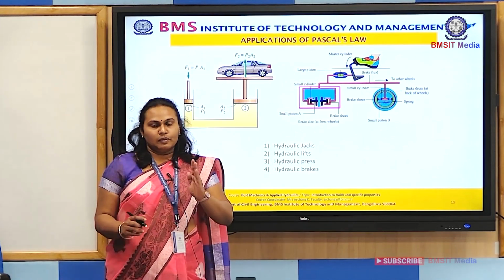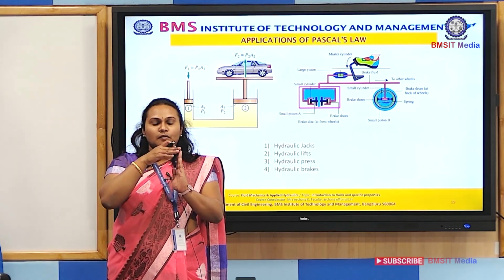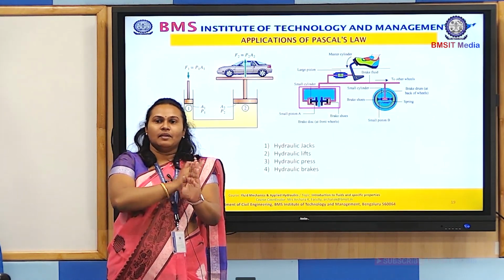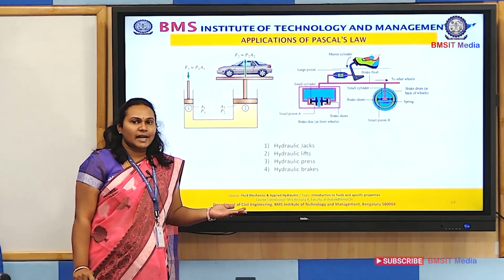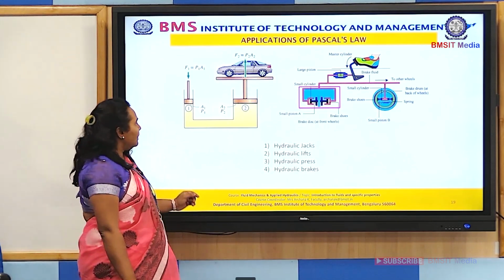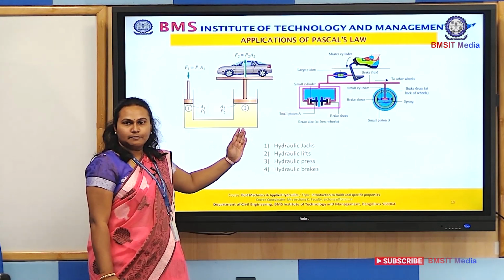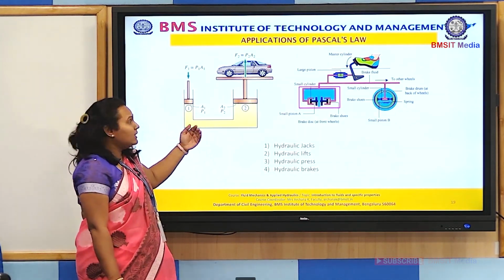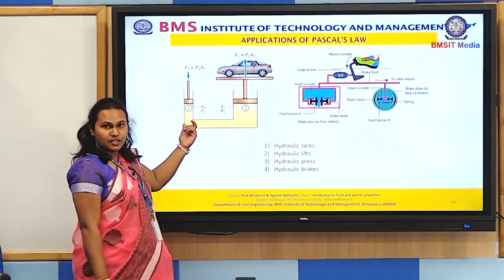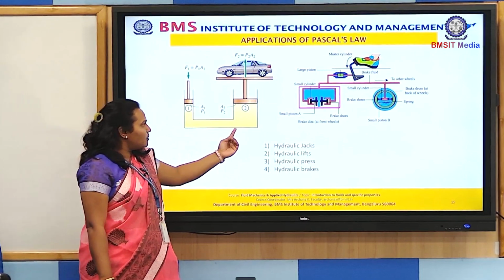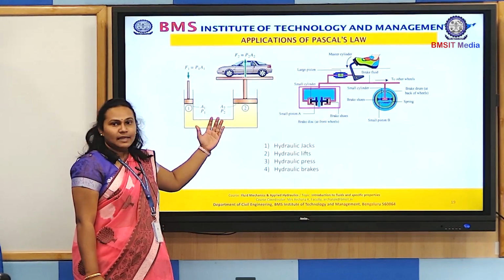As I told you, Pascal's law states that if a pressure is applied on any object, the pressure from the fluid will be the same in all directions. If you look at any hydraulic brake or hydraulic jack or hydraulic lift, this works on Pascal's law. Let's assume there's a plunger on the left hand side and a ram on the right hand side. It's a beautiful concept that when you apply a force on this small cross section area of a plunger, the plunger and the ram are filled with a fluid, maybe oil or any gas,